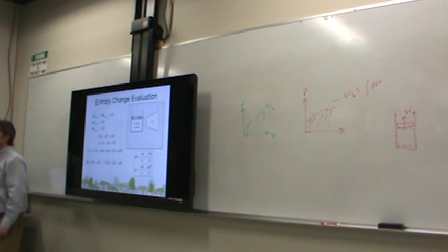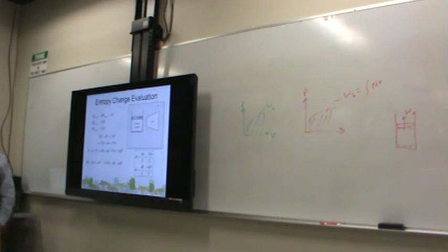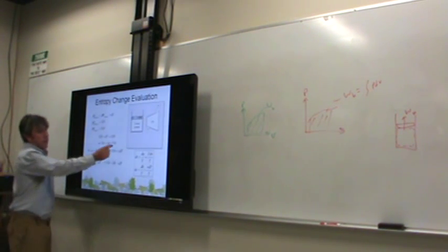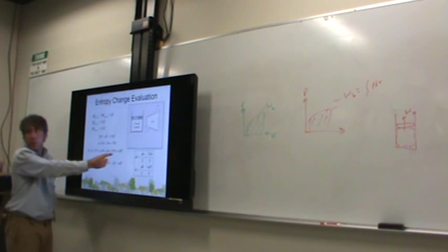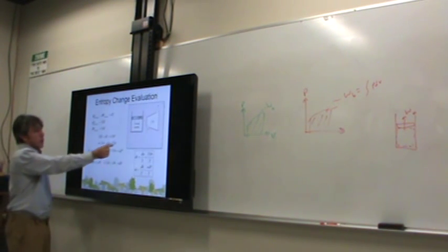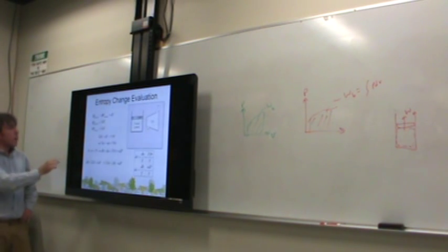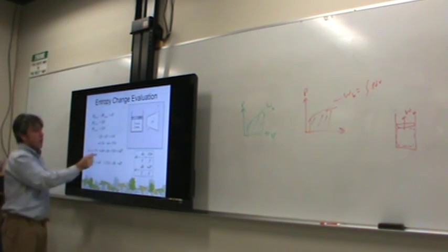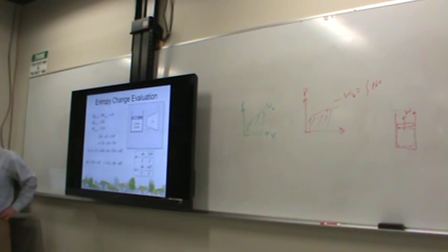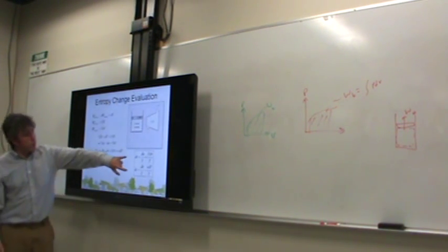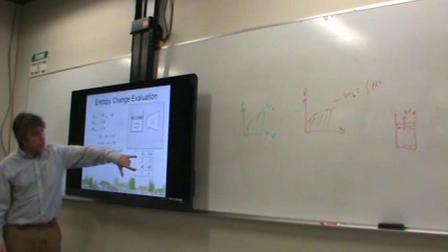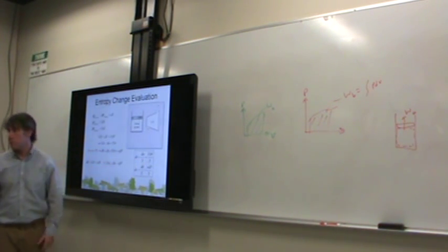So you kind of split the work into two separate things. Like you got TdS as part of the work and here's this PdV right here. Is this the part you're talking about? Yeah. This PdV, all we did was we took a differential of both sides of the equation. That way, because we already had differentials up here, and we needed to plug in differentials. So the point here is that we get not just one, but two equations that relate entropy to properties of the system.